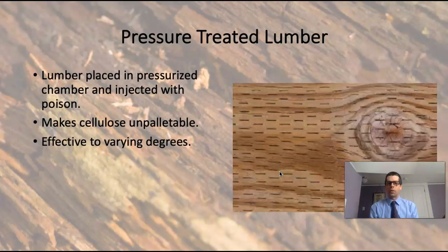The lumber we have on the West Coast is resistant to the pressure treating process. I'm not sure what good painting a little bit on the end is going to do when they have to puncture this stuff. Okay, so maybe it's the end grain and it'll help absorb it more readily. But either way, I've gotten to the point where I just paint the end, and I feel like as long as it's sealed up, it's going to help out tremendously. And I've pulled lots of rotten wood out of the ground, and the stuff that's been primed or painted has held up a lot better than something that didn't get any treatment at all. Okay.